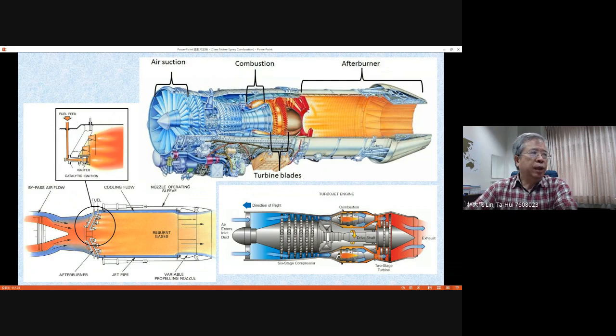Usually the spray atomization will occur before they reach the afterburner, and we will have behavior more related to gaseous combustion in the afterburner. Then we call these the spray systems in the afterburner system. Actually, they are more related to the spray atomization, and for the flames in the afterburner, they do not have too many droplets. They are more purely modeled by a gaseous turbulent premixed flame.